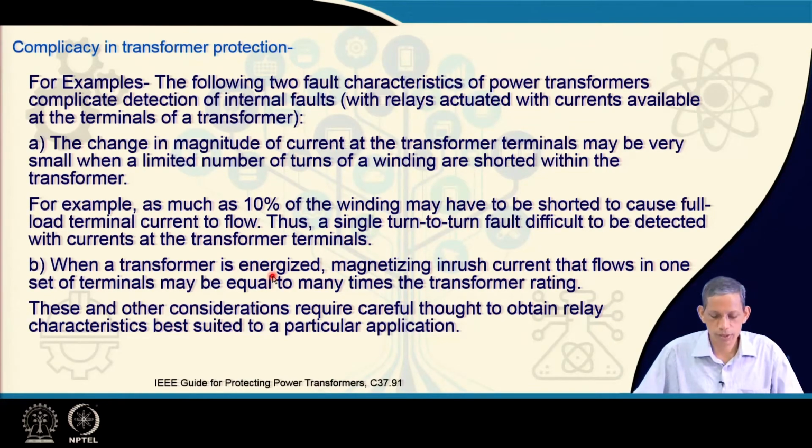Therefore, a differential current will be there, and this current may be many times the transformer rating. So even though it is not a fault, how do we tackle these situations? There are several other issues, which we will discuss in the later part of the module, that lead to challenges for transformer protection, and they must be carefully addressed in any protection scheme designed for a transformer.